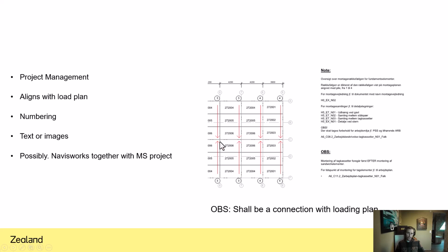So also when you make the element list here, you will have, say, I have 1, 2, 3 types, and then I do the same 1, 2, 3 types. You'll have another type here, and another type here, and another type here. Okay, so have that in mind. The fewer types you have to do, the fewer drawings you have to do, and the easier it is for the production, the manufacture of these elements. So just be aware of that when you make the cutting list and the element list, please have that in mind with thicknesses and sizes and length.